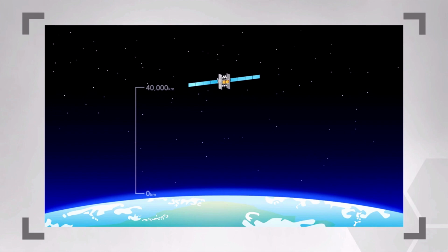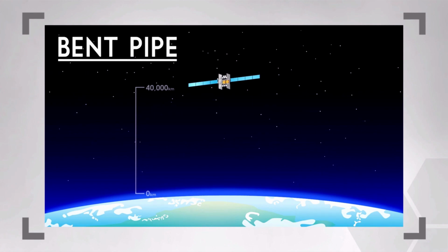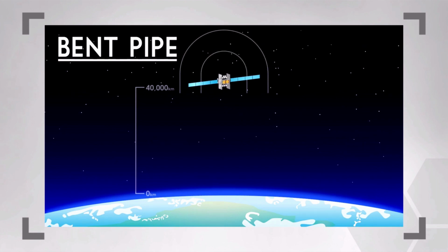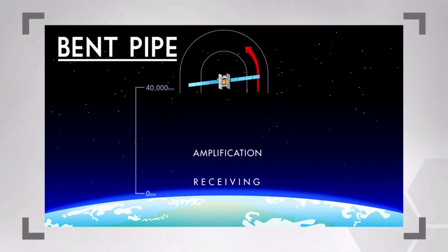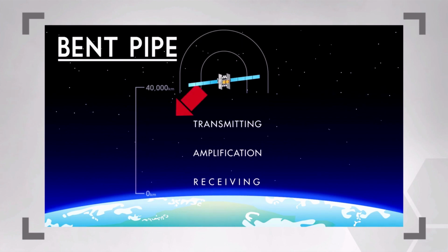Satellites that are selected to fulfill tasking as the conduit for receipt and retransmission of received data and media are often referred to as a bent pipe. This term comes from the order in which signals are received and then retransmitted. Shown here in our simple diagram of data transmissions, after receipt of the signal, the uplink signal is then amplified, translated to a downlink signal, re-amplified, and directed back to Earth via high-gain antennas. It flows in a similar fashion to that of a bent pipe in space.